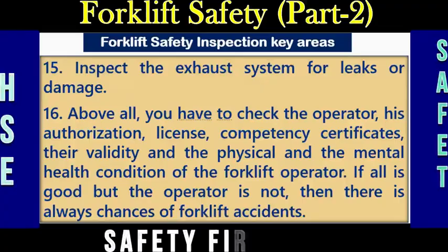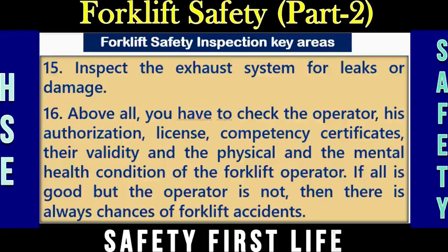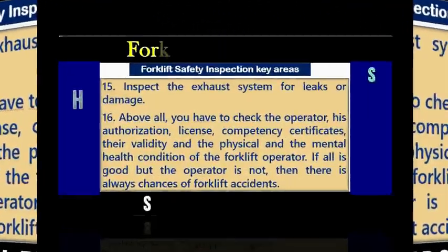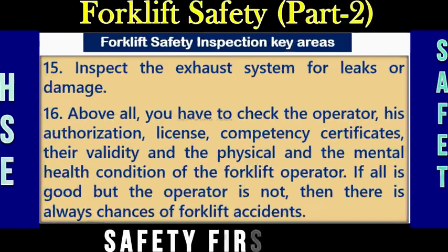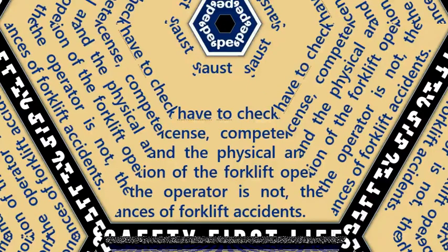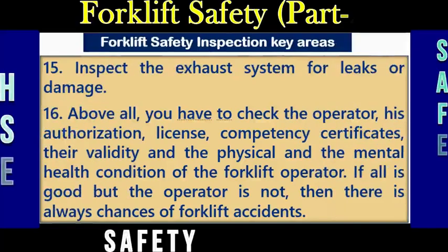And the last point, point number 16, above all, you have to check the operator, his authorization, license, competency certificates, their validity, and the physical and mental health condition of the forklift operator. Remember, if all is good, but the operator is not, there is always a chance of forklift accidents or incidents.